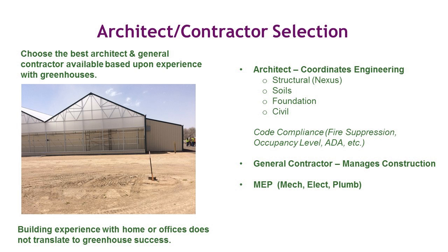There is a lot to be said for having someone who knows the tricks of the trade for building greenhouses. There are certain little things, such as the light deprivation system and how the flashing goes on. An experienced greenhouse builder may want to put the flashing on the trusses before he lifts the trusses into place, for instance. Things like that save time. That's what you're going to get with someone who knows how to build greenhouses.